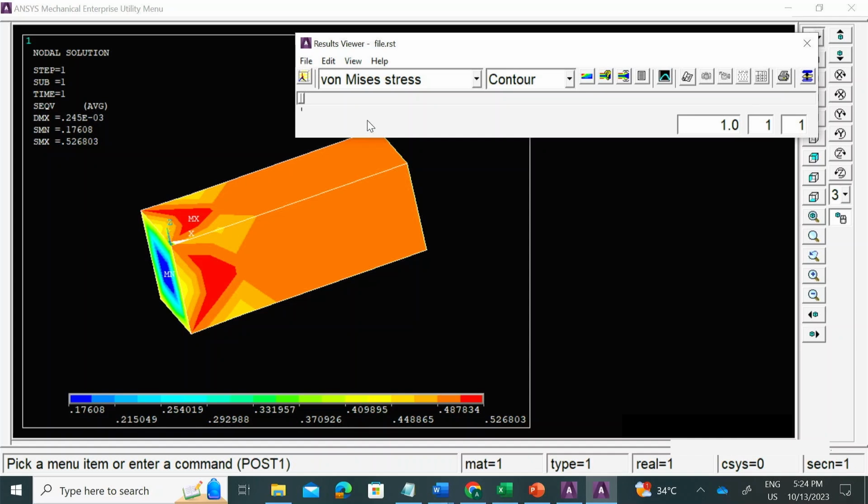This is another point to be noted. I have applied a linear mechanical property with a modulus of elasticity and Poisson's ratio, which is not typically the case with soft tissues, as I've explained repeatedly in several classes. So what I would like to mention here is stress upon strain is given as the modulus of elasticity. That's the calculation. So whatever you are seeing in stress values, you will see a very similar representation. So my modulus of elasticity was 10,000. So you will basically see the strains in terms of a 10,000 multiplier and very similar distribution.